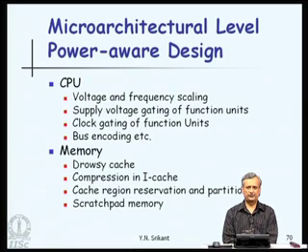For example, if an arithmetic logic unit (ALU) or a cache line is not being used, it is better to stop the power supply to that particular function unit, so that the static power dissipation in that unit is going to be 0. So, supply voltage gating of function units is another technique at the microarchitectural level to control energy consumption.